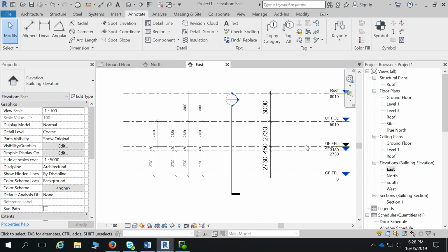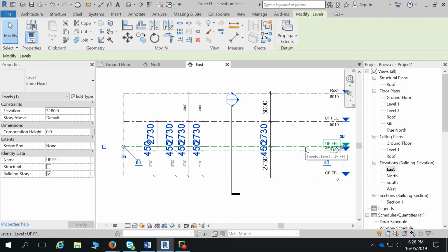So if you select your level, some of you may have already found this by walking around the room. There is a little zigzag elbow thing here. If you select that zigzag, it actually breaks your level line. And then it's got two blue dots that allow you to adjust the line. So there's a bit of an idiosyncrasy here. The first dot coming off your level can't go past the second dot, and vice versa.